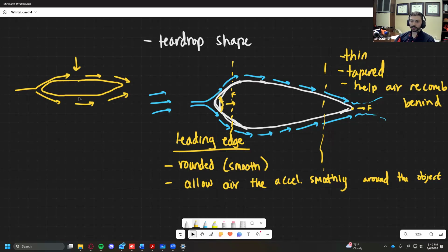There's nothing else. But in the real world, we cannot use fabric, right? One of the other limitations sometimes is going to be the structural members, because we have to structurally support this object. And so the thinner you make it, the weaker it gets, so you're more likely for that bending load to basically crack. Dr. Hannon also brought up a really good point, which was harmonics. So the thinner you make something, the more tendency to bend. I'm sure you've all seen that, right? Because your moment of inertia drops.